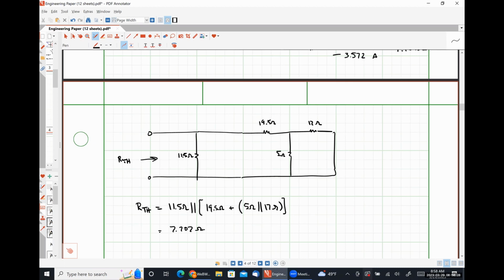All right, so just to recap things here. When you are finding the Thevenin equivalent circuit or the Norton equivalent circuit with respect to a particular circuit element, you remove that element from the network and do your analysis. Removing that element leaves behind a set of terminals that you use to measure the Thevenin voltage across, look into to find the Thevenin resistance, and short circuit in order to measure the Norton current.